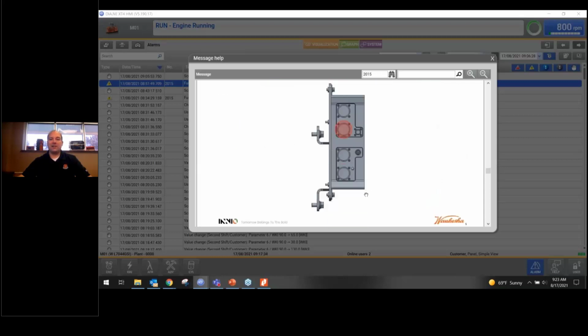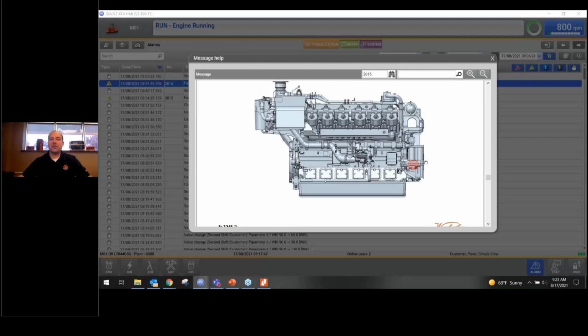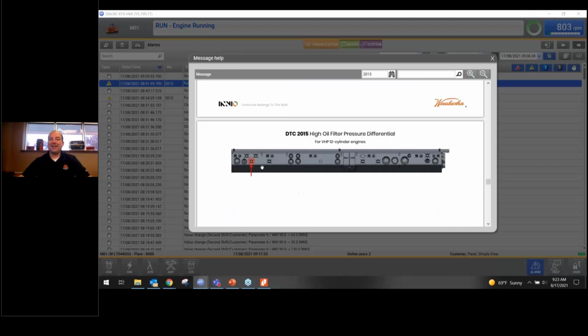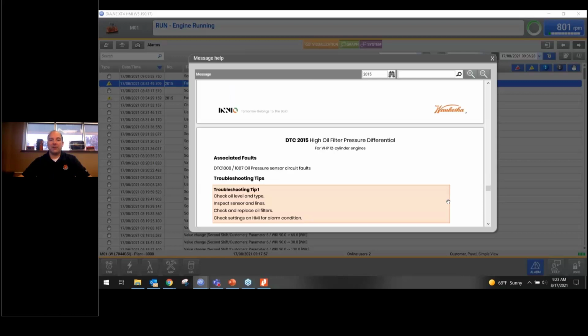And it identifies that on the side of the ECU, we've got our harness connections. So this is going to be A, B, and C, and D harness. And it is identifying that this would all go through the C harness. It lists where my pre-filter pressure is for looking at it, and then it also looks at where my location is for where that plugs into the rail.